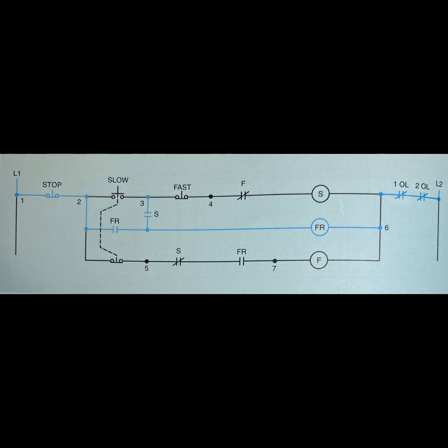Mistaken reversal caution. When multi-speed controllers are installed, the electrician should check carefully to ensure that the phases between high and low speed windings are not accidentally reversed. Such a phase reverse will also reverse the direction of motor rotation. The driven machine should remain disconnected from the motor until an operational inspection is completed.